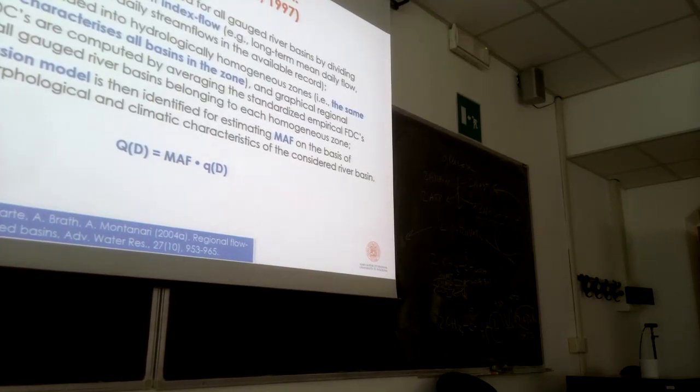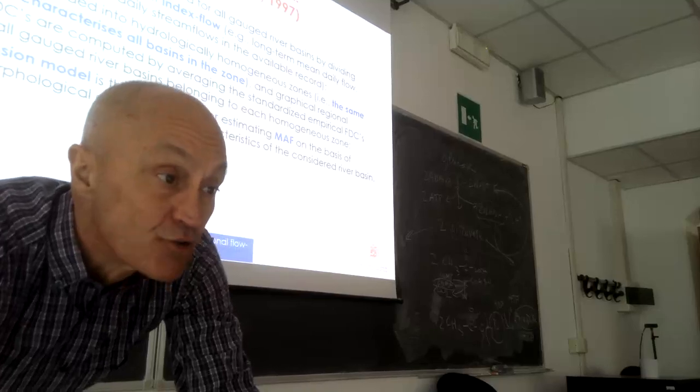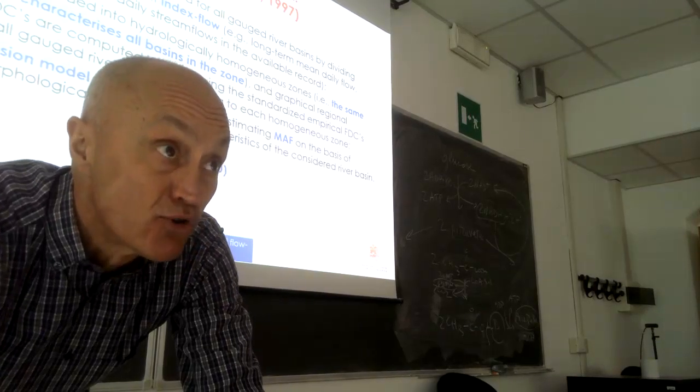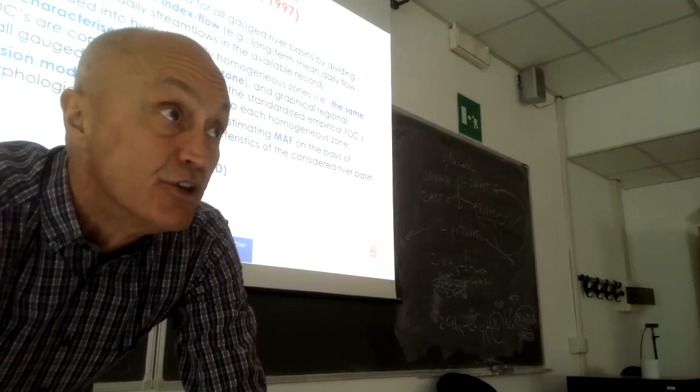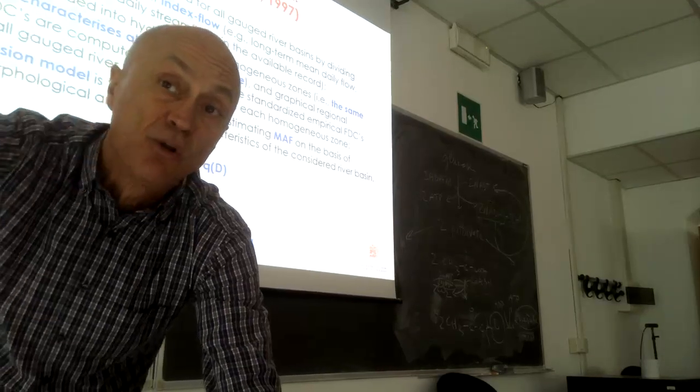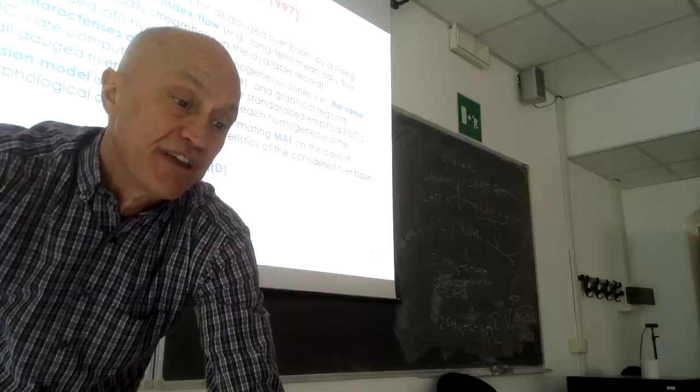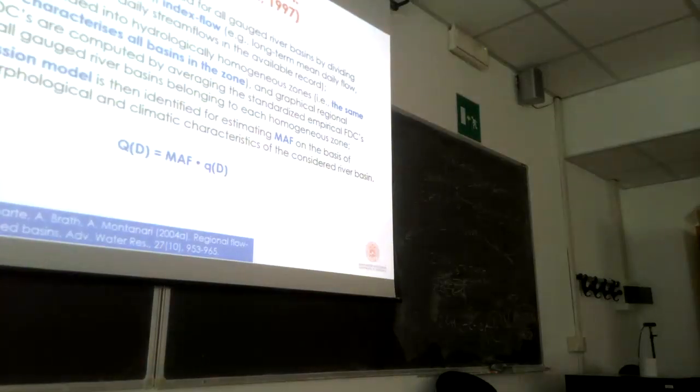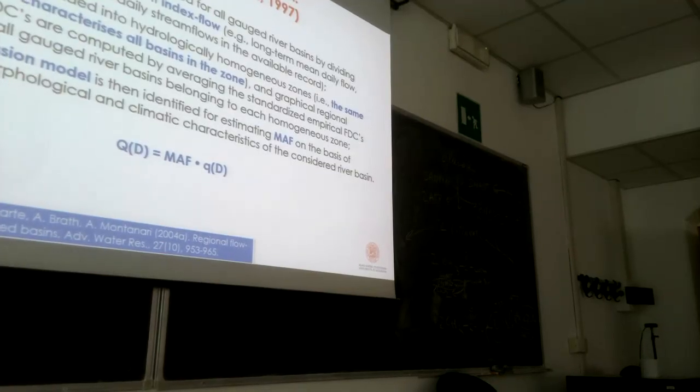Its main idea is very simple. The flow duration curve is what? Flow duration curve, as we know, is a representation of stream flow with duration, right? Here I have stream flow, and here I have duration, and this is the discharge or stream flow associated, sorry, this is duration D, sorry about that, and this is the discharge associated with the duration D star, okay?